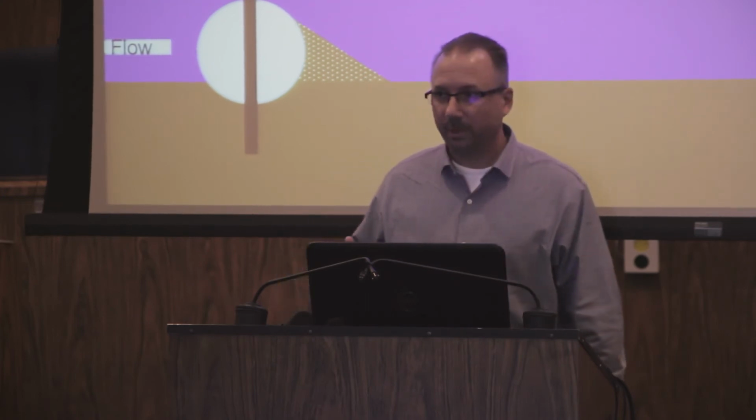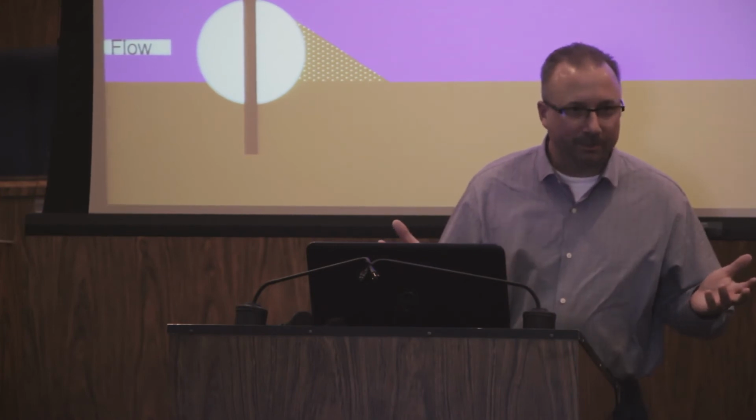And fiber rolls are not filters. A lot of people think they're filters, but they are not. I can prove that through a very high-tech story. Three little pigs. What did they build their house out of? Straw, right? Why? Because it keeps the rain out. What does much of the third world, many places in the third world, build their homes out of still today? Straw on the roof. Why? Because it doesn't let the rain in. You pack straw into a fiber roll, it's not going to be a great filter.